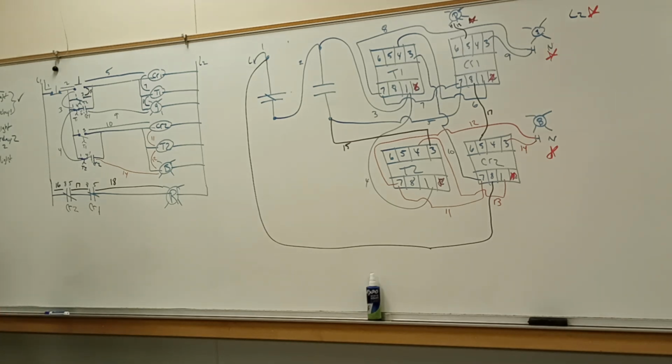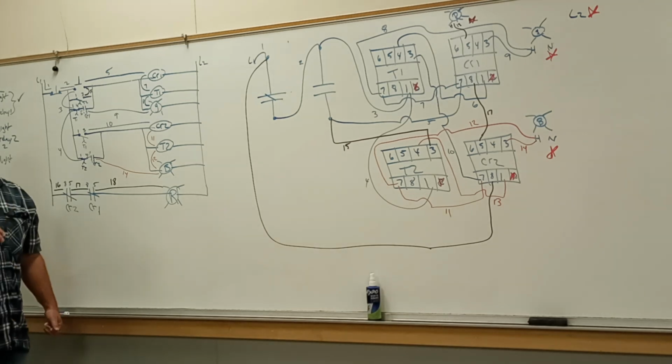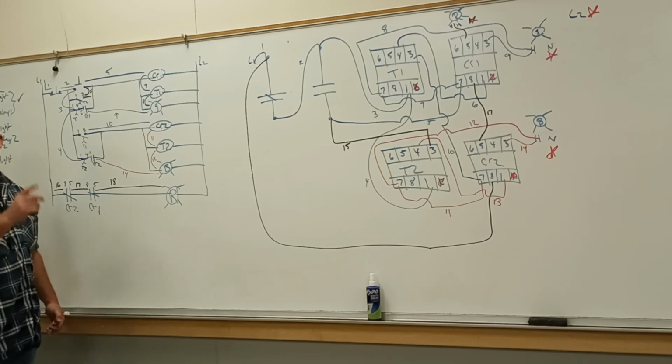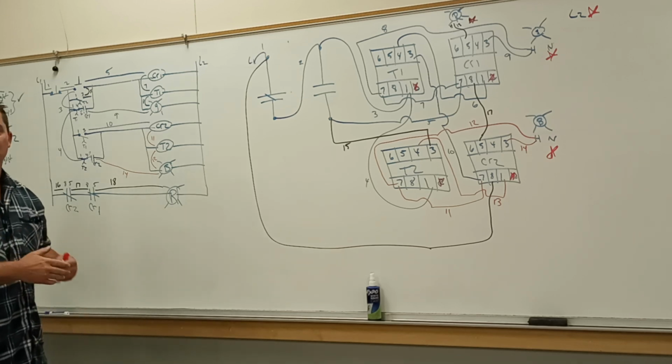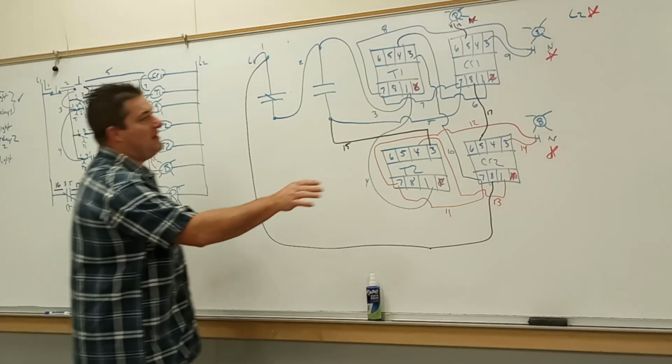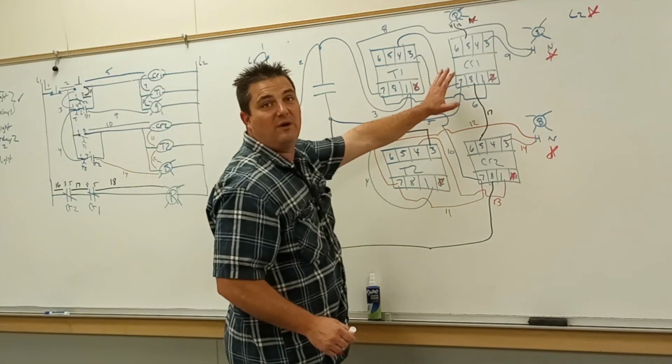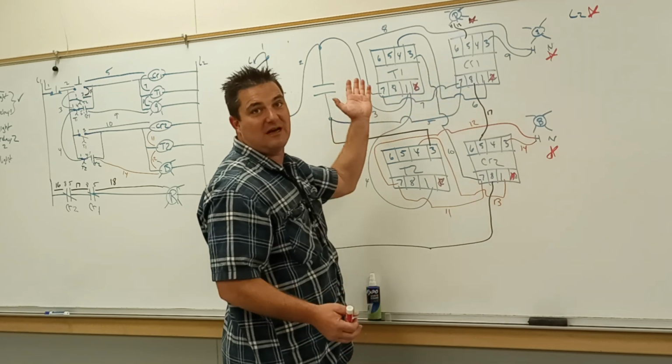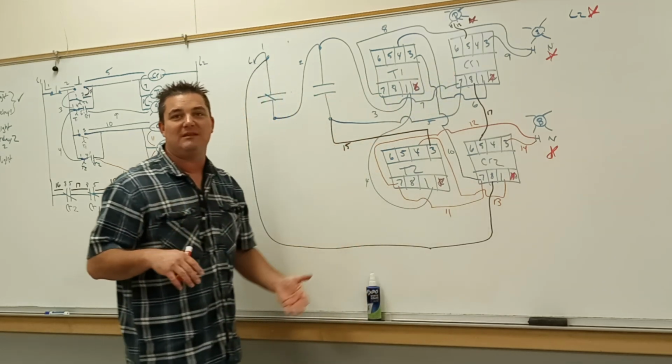All of your relays, all of your timers, all of those are going to have a maximum ampacity. Maybe, with whatever outputs you had, using that one set of contacts would have been over the permissible current. Then I could use maybe the coils for one side and the lights on the opposite side, or something to split that energy.